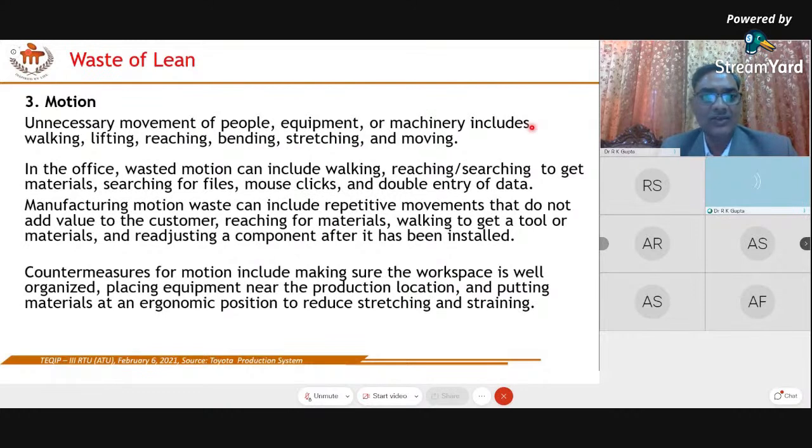So that we call the composite part concept. In this composite part concept, we are doing the external cylinder design features, that is included in the turning. Face of the cylinder, like the facing. Cylindrical step, the turning. Smooth surfaces, external cylinder grinding. Axial hole, drilling. Counterbore, counterboring. Internal threads, tapping. So these are the corresponding operations with the design features.